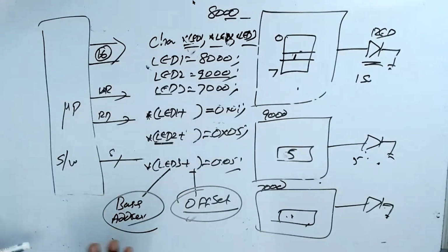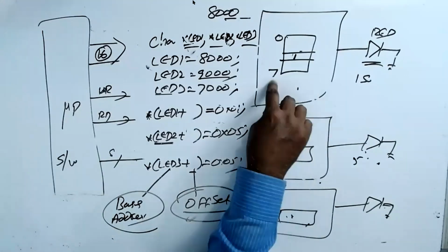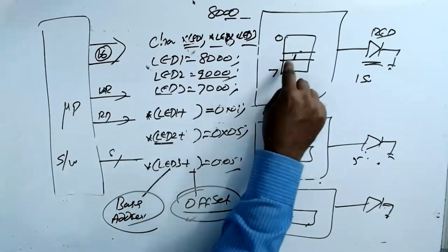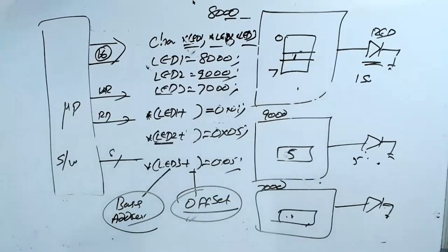But initially don't do that. Initially start creating your own .h file. As I told you, you need to first understand the basic principles of how offset and base work. The base is not for a particular register, but for a particular controller. I am using 3 controllers. All are the same type of controller since they have the same offsets. Base addresses are for controllers, not for registers. The offset is for the register. So base address plus offset gives you the particular register.